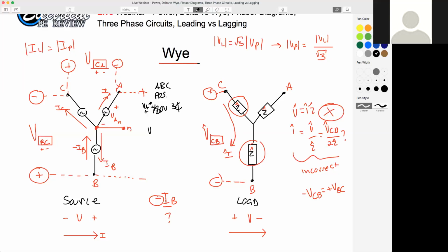Okay, that's fine. So this is VAB. Sorry, this kind of tripped me up really quick. So if my voltage from A to B is positive 480, and I asked you, what's my voltage for VBA? It would be minus VAB. So when we are assigning references, the positive end will be at the positive end, and if we're incorrect in our assumption, then we simply multiply it by -1. Mary, did that answer your question, or were you referring to the subscripts?